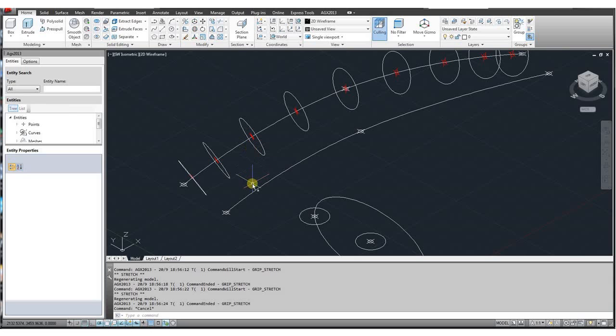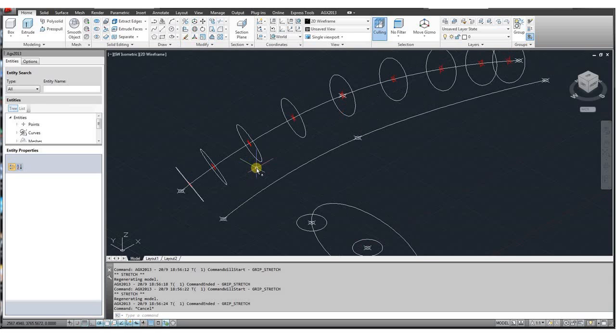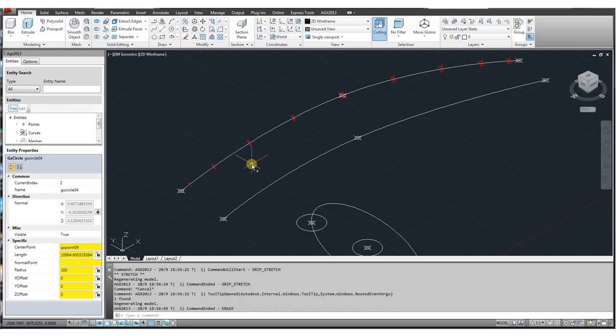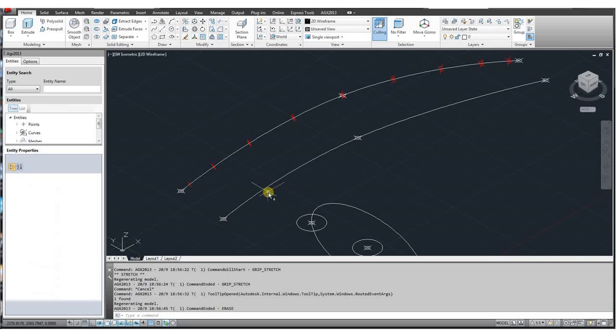Now let's use the radius point mechanism, and I just want to show you what that yields. So I'm just going to get rid of these circles. Okay, now we're going to need to create the same number of points on this spline, and then this spline will be used to control the length or the radius of each circle, and it will differ.